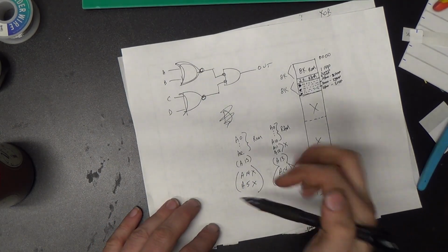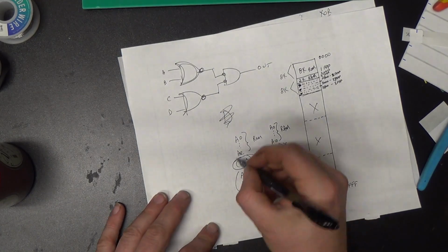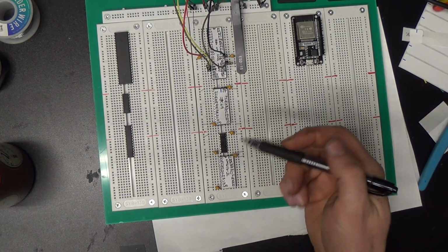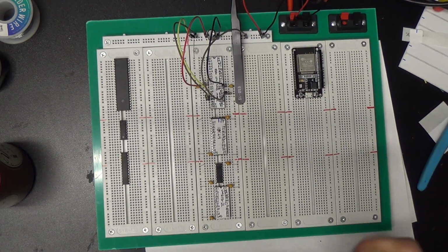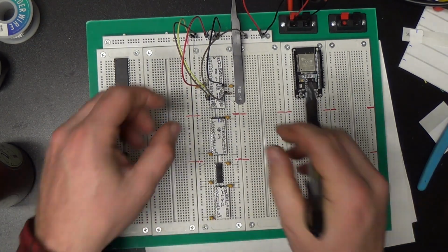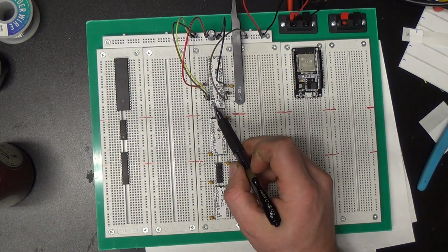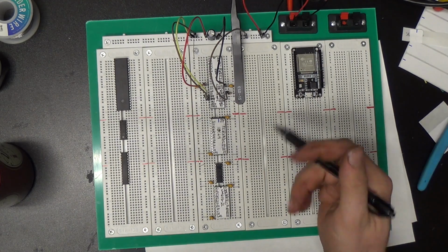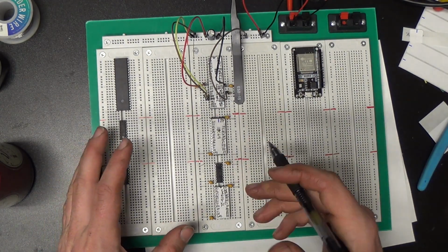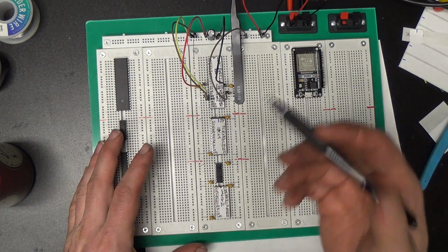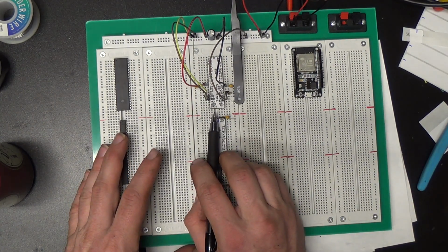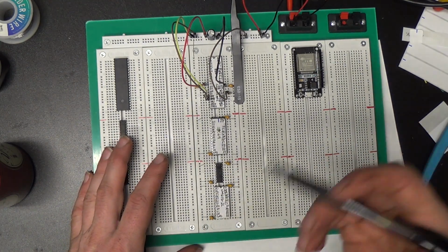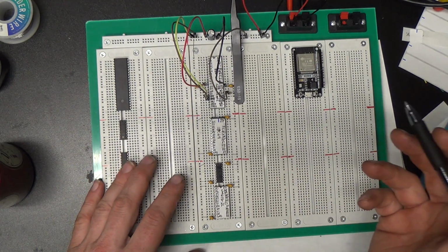using the A13 line, only the A13 line. Recall that when we examined the Z80 CPU and looked at all of the pins on it in a previous video, it has a memory request line, MREQ, down here, which is active low, that specifies when a memory cycle is going on, as opposed to an I/O cycle. I/O cycles are specified by this I/O request line being asserted. It's also active low. So that's for reading the keyboard and writing to the screen, or to the serial port or whatever, right?